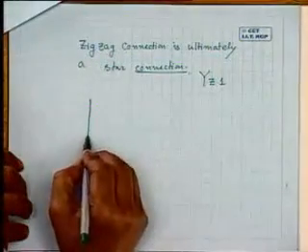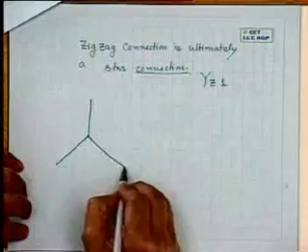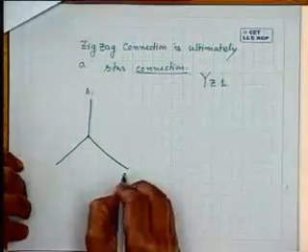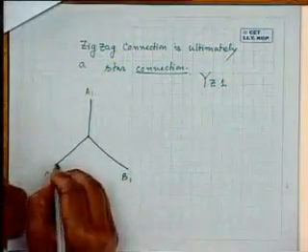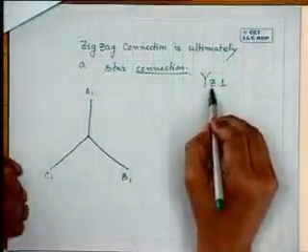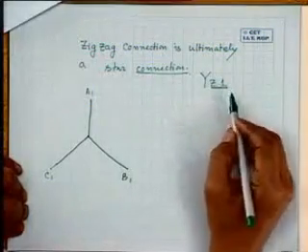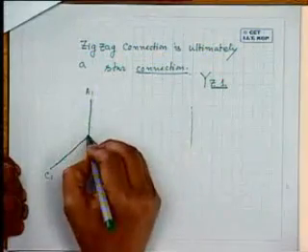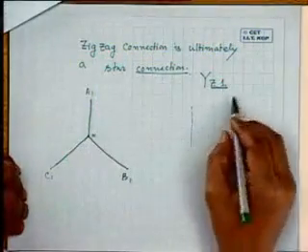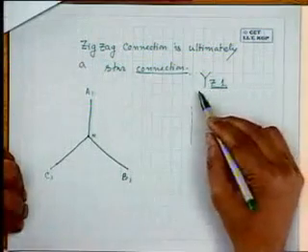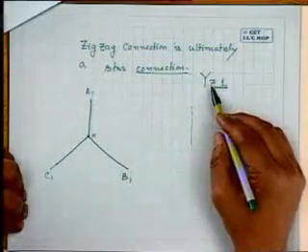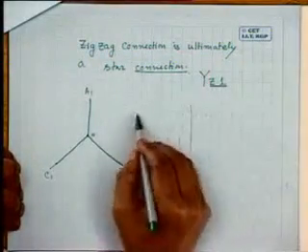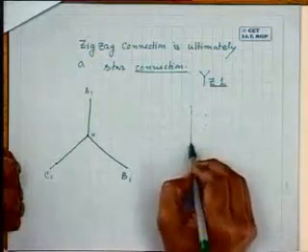So how shall I go? This is the primary voltage. Here I will once again draw. This is the primary. This you just listen carefully, what I am telling. A1, B1, C1. Now on the secondary side it is one connection. Therefore A phase voltage where it should be, I will first draw a line parallel to this that I have drawn. And secondary voltage will be lagging it by 30 degree. Is not? It will be lagging it by 30 degree.